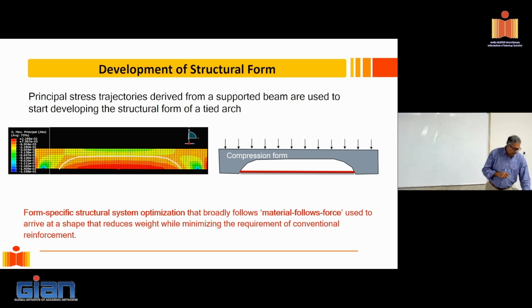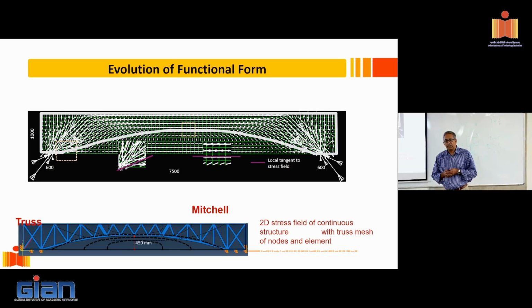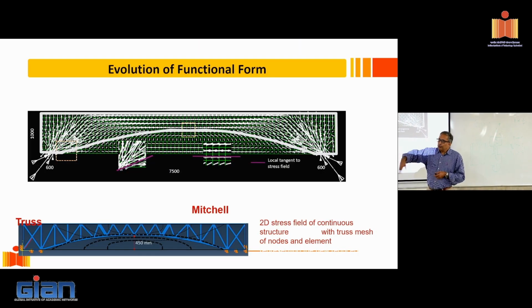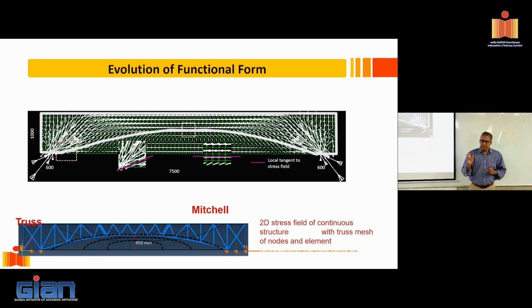Well, we can. Actually, what we can do is something that follows along the lines of topology optimization. Except when you do topology optimization, it becomes a mathematical exercise. You determine the final shape outcome of this structure given performance criteria, be it deflection, strength, capacity, what have you. But then you have no control on the shapes that come out. You may get filaments of different widths located in some random location. A mathematical exercise. What is the problem we have? Our filaments are more or less confined to be of the same width.